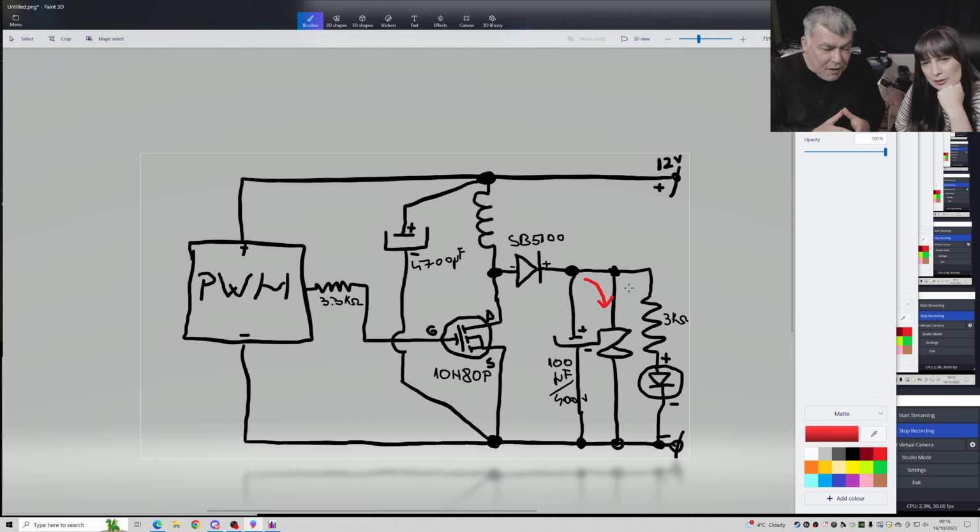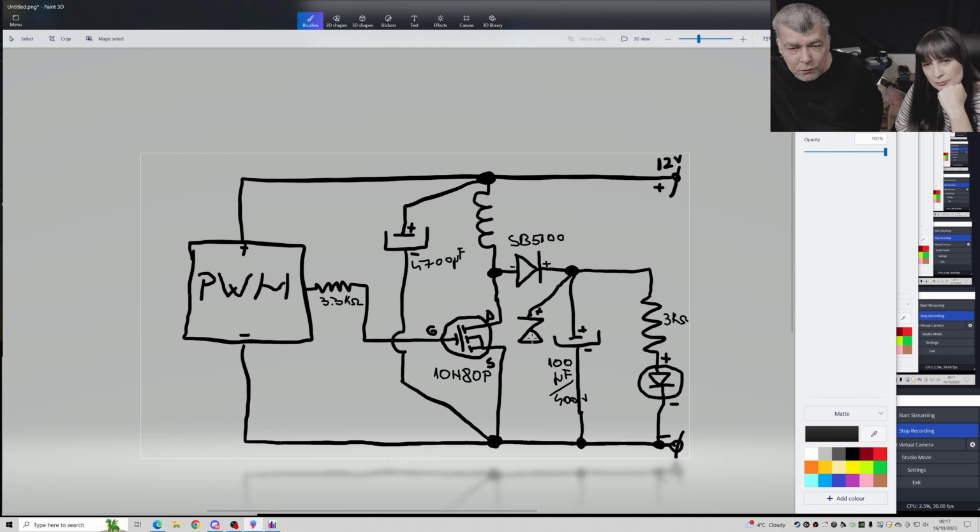All right. Indeed, this is a current boost converter, and you trade the current for the voltage. But even this current will burn the diode. First, let's use a Zener diode because we need something to let us know when the voltage passes through. So we're going to use a Zener diode around 15 volts. So we know when the voltage goes over 15 volts, the current will flow through the diode, right?